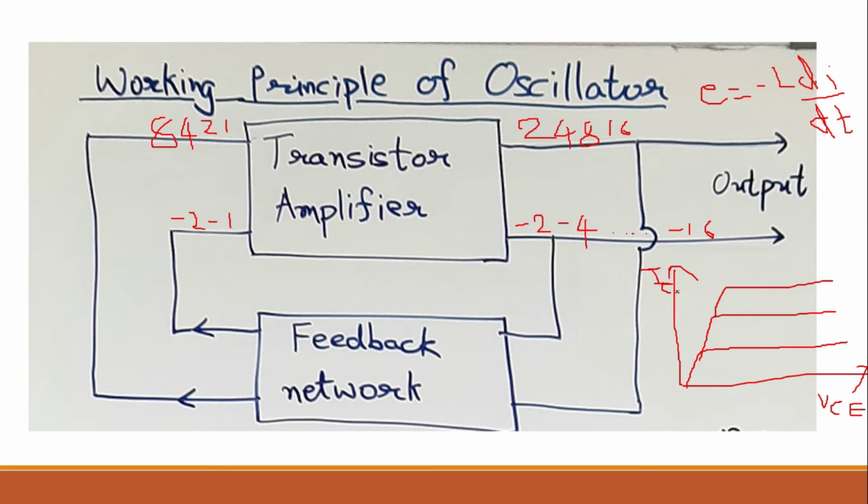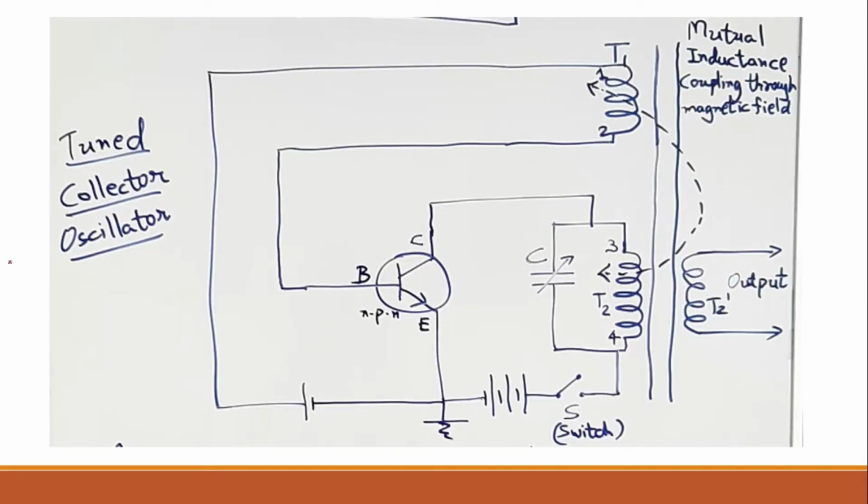As this IC becomes constant, there will be no change in current for the inductor, and if there is no change, then the voltage will become 0 and again it will go down. And after some particular level the cycle will get repeated. So due to this particular interesting property of transistor, we can use transistor amplifier along with the LC oscillator to obtain sustained waveforms.